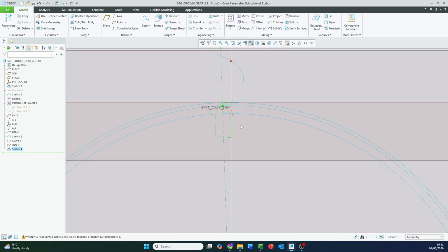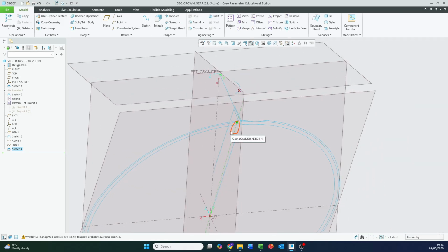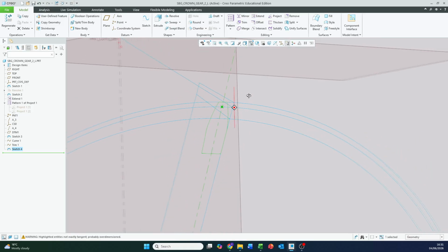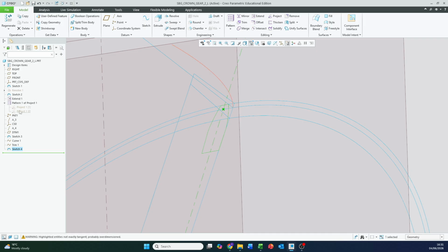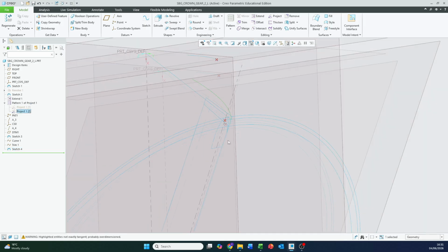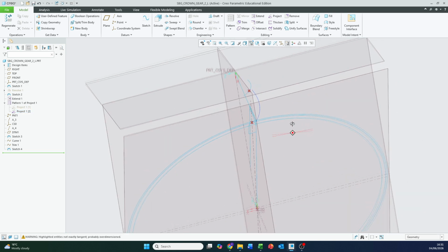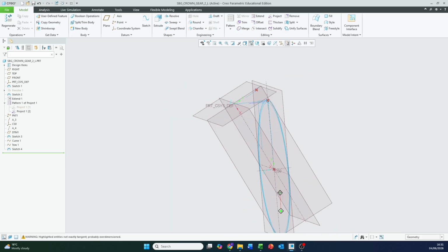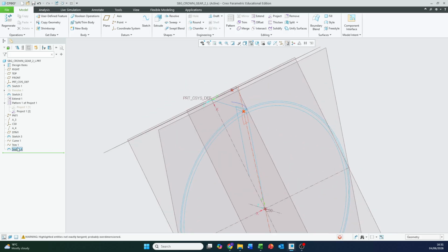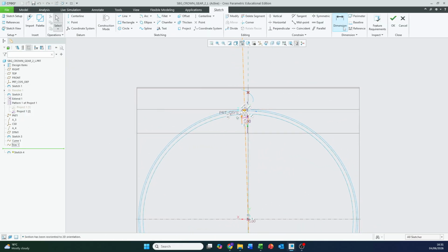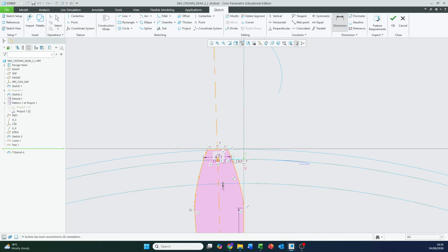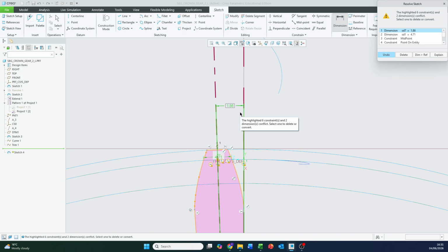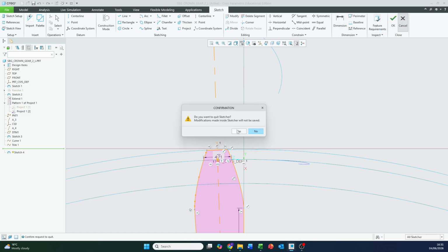Press OK. And the same thing again, I want to pattern this sketch so that I can have it positioned here to be in line with our projected curve copy. So this is where I went wrong with the first one because I used the wrong rotational axis. We have to make sure we use the right one this time, won't we? So let's go back into this sketch. And I need the angle between the midpoint here and the y-axis, 1.86. Remember that value. Exit out of it.